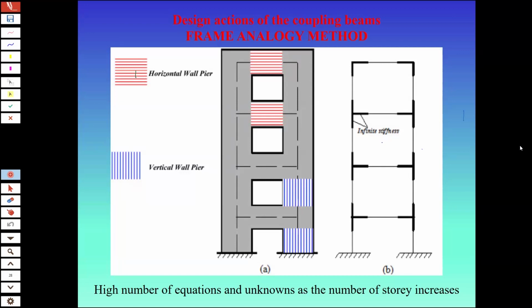One rotation here, one rotation here, one rotation here, one rotation here. So one rotation in each node times 2 because you have 2 shafts. So 1, 2, 3, 4, 8, plus 1, 2, 3, 4 displacements. So it's 12 for a 4-story.